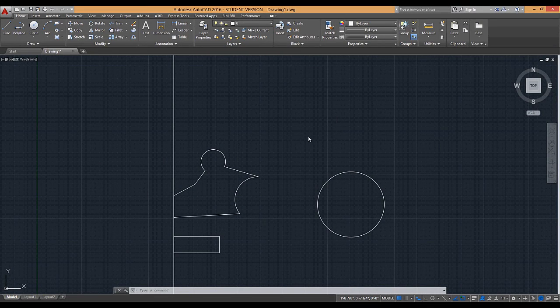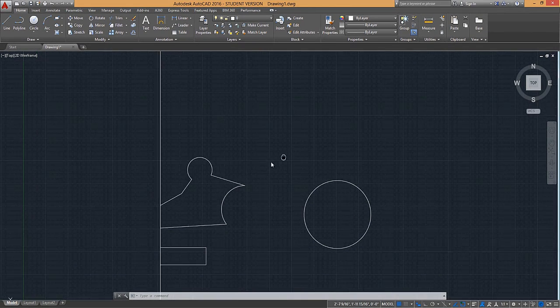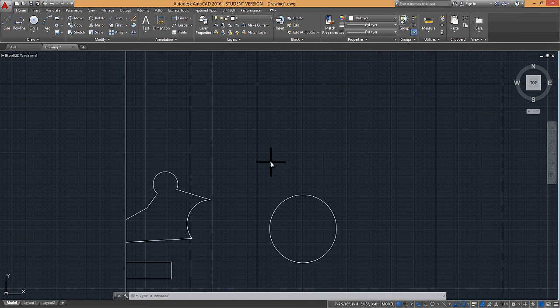In designing more freeform, a lot of times we want to move away from just drawing lines. So we can create curved lines in the form of splines. Splines are a really great tool when you need to draw customized curves. They can be stretched and adjusted using the grips, and you can also edit a spline with the spline edit command for additional vertices. As we talked about before, we can join polylines and splines into one object by using the pedit command and the join option. Like how we used pedit last week, we can also edit splines using pedit.